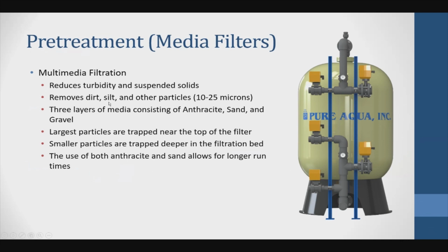Now, like the filters, like what we mentioned, it has 5 different valves. The feed water is going to go from here. When the filter is going through the filtration mode, that means this valve is open, this valve is closed, this valve is closed, this valve is closed, and this valve is open.